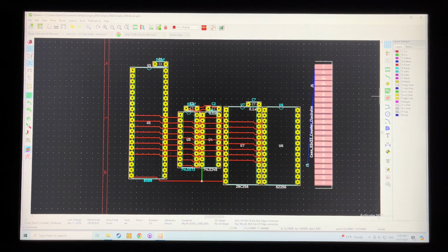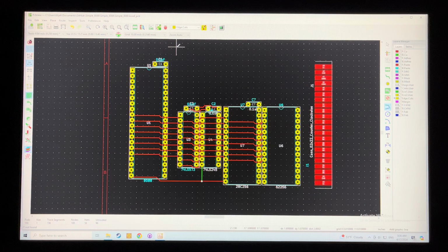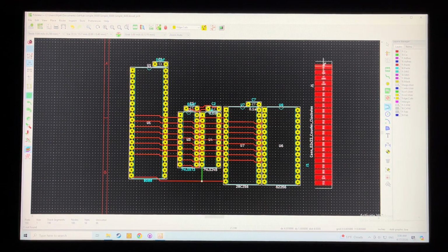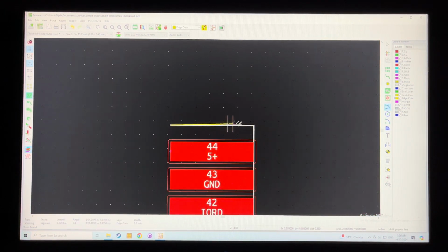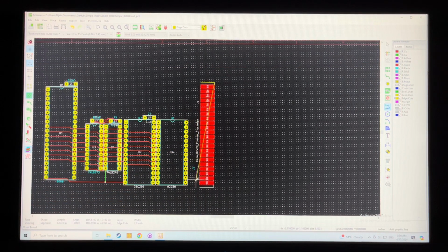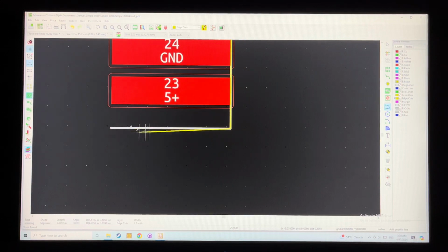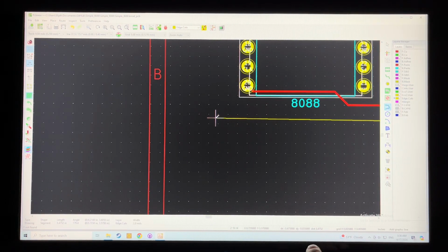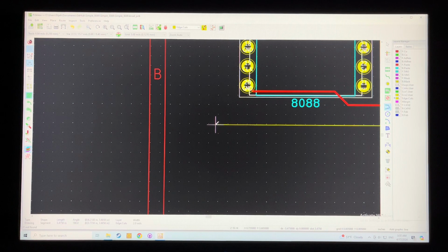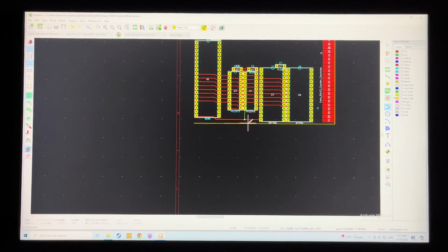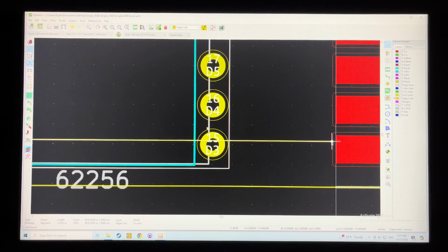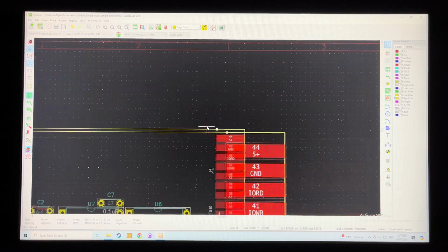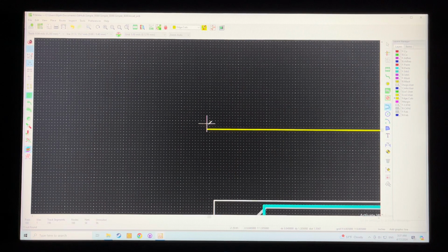So come over here, edge cuts, use this polygon. On this particular footprint here, I've got this gray line to show me where the edge cuts need to go on this particular piece, because it's an edge card connector, and I've got it all measured out where I want it. So I just trace it, and then from here I'll just go over. If you look on the bottom here, you've got some dimensions. You can just arrow until your dimension Y, in this case, is 0, and that means it's a straight line. And then I might just cheat a little bit, and I just select it and hit Control D, and then I bring it up here so I don't have to eyeball how long it needs to be, and then I just select, and it'll snap to the end like that.